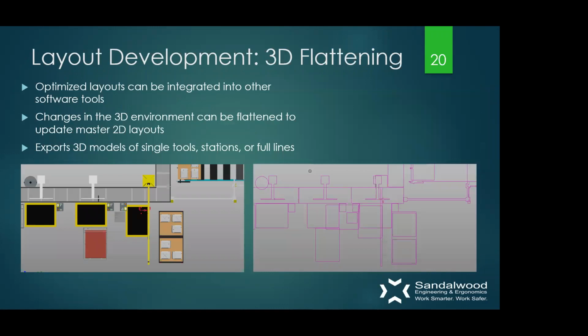And then obviously we want to be able to feed this information and all the great work that we do in Process Simulate back into other tools that our clients may be using, which is very easy to do. So changes in the 3D environment can then be flattened to update, let's say, a master 2D layout in AutoCAD. You can see an example of that on the bottom here, where we've got the 3D resources and overhead view on the left, and the flattening that Process Simulate generated that can then just be directly imported into AutoCAD on the right.